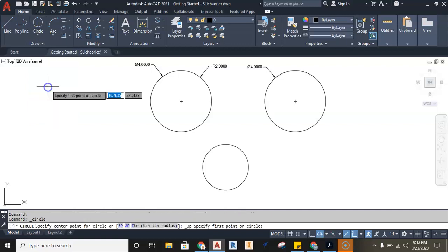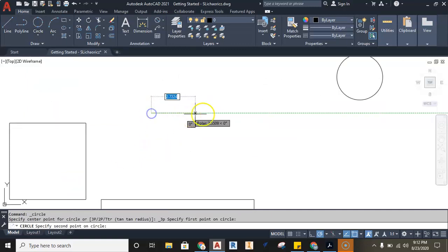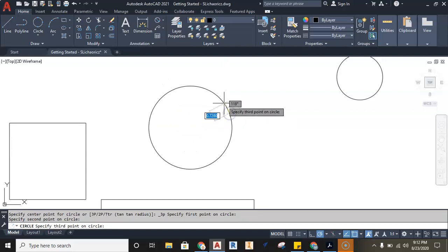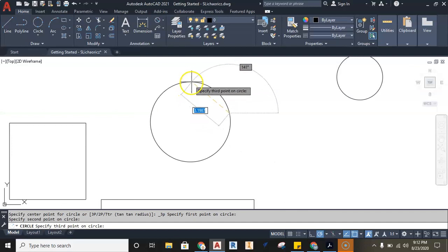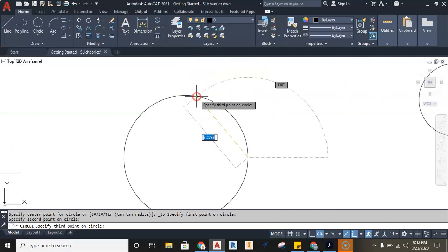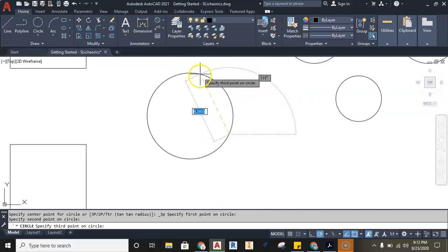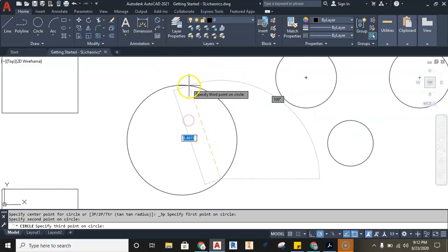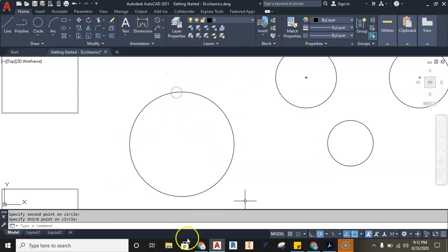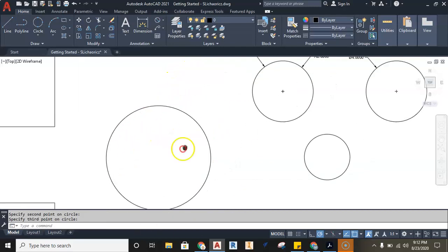This time it'll be 3 points, and the first 2 points are going to be from one side to the other. This is actually very interesting, how these 2 points slide around almost as if those points are tangent. They're not being called tangent. There's a different tool for that, but this picks 3 points to create a 3-point circle.